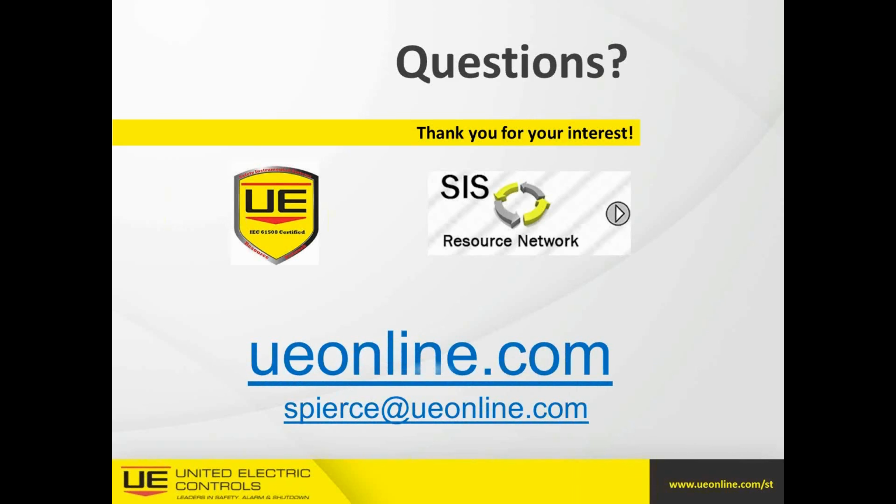The only thing you're going to use the NAMUR output for is to get 24 volts to the device, and now you can switch your final element direct. And you don't need the PLC because you've got the I am working diagnostic output that you can run back to your basic process control and say, hey, I'm either healthy or I'm not.